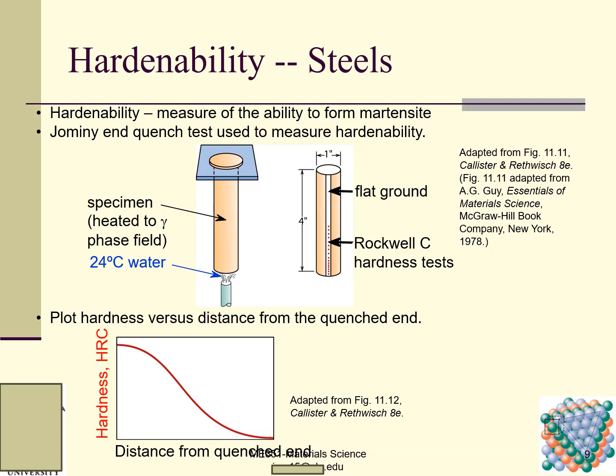As a result, at this point it should have the highest HRC hardness, and it goes down as the distance from the quenched end increases. You can see it goes down this way. Any questions regarding this slide? Because this slide is very important, I want you to pay attention to several important points.